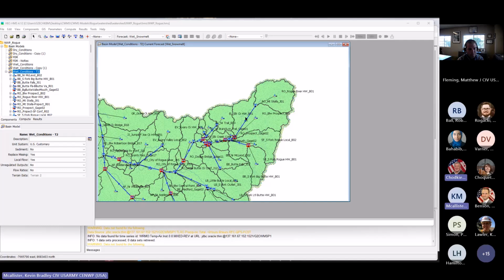Okay, so then you would probably just merge them at that point. That's what I would suggest. But just for fun, before you move forward in a final direction, you can have two separate basin models, one merged and one not merged, and run the same simulation. And you can start diving into the results and see if they're different in a bad way or just different. When I start doing all the merging, I'm just duplicating this one and creating a new one off of that duplicate. Perfect.